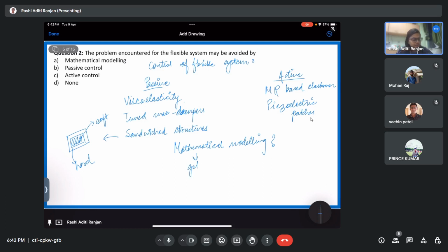Get the nonlinear differential equation. And then what is required? Once you get the differential equation, use the method of multiple scales, use the method of perturbation, use any other method that you want to get what kind of solution it is going to give. Use the Floquet theory to find whether the system has a periodic solution, a stable or unstable periodic solution. Use numerical techniques in order to know how the system is going to behave wherever the method of multiple scales or these kinds of methods are not going to operate. It makes your life easier.